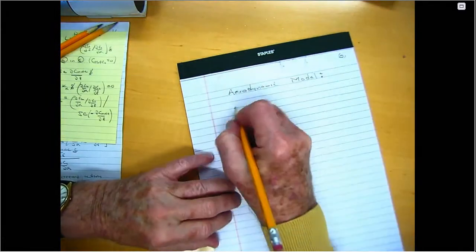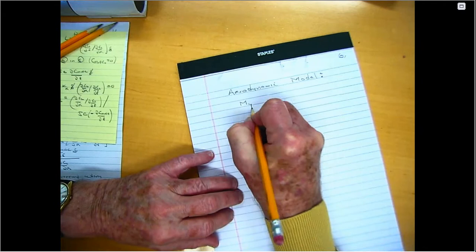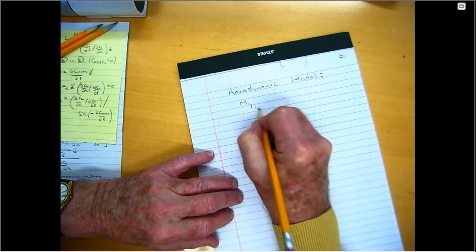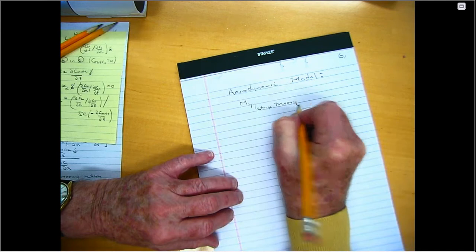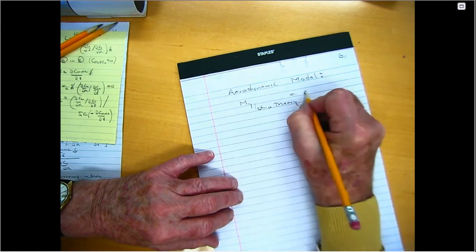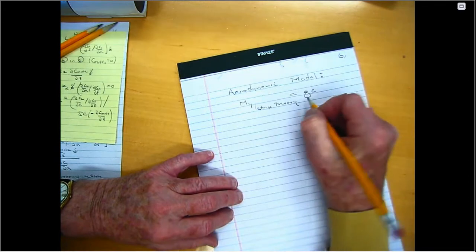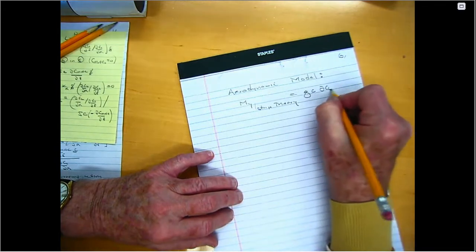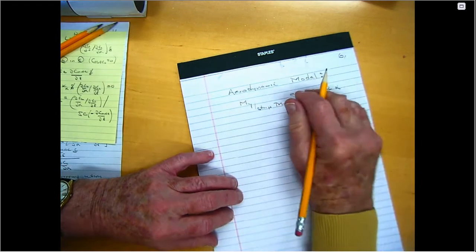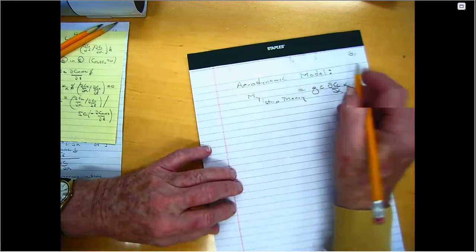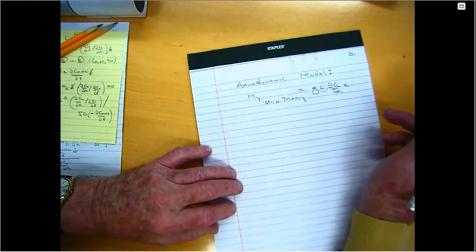So our moment, I'm going to call it M sub y, but now in strip theory, rather than having q times the area, I'm now going to have just q times c times dCL d alpha times alpha. And I'm not allowing my control surface yet, but we can do that later if you like. Now, this has the dimensions of length, whereas before it had the dimension of area.